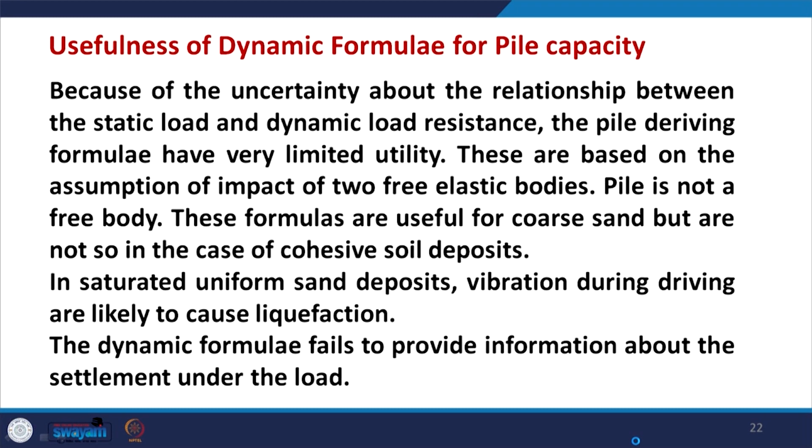These formulas are useful for coarse sand, but are not so in the case of cohesive soil deposits. So for sandy soils they are better, but they will not give good results when you talk about clay. In saturated uniform sand deposits, vibration during driving is likely to cause liquefaction. That is one of the factors which also needs to be accounted for, and the dynamic formula fails to provide information about the settlement under the load.